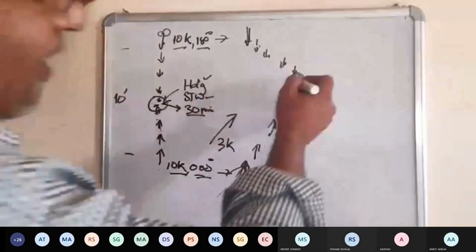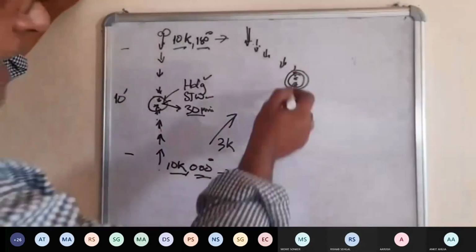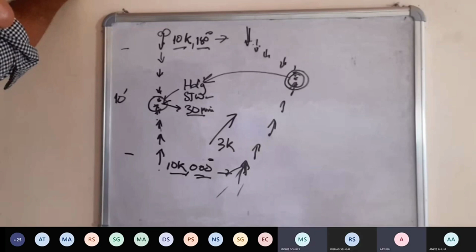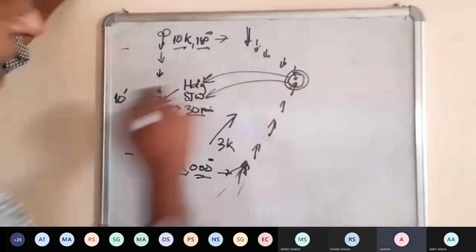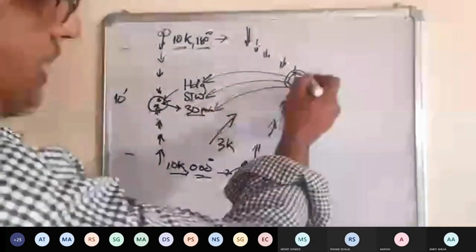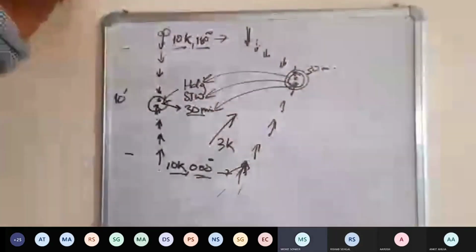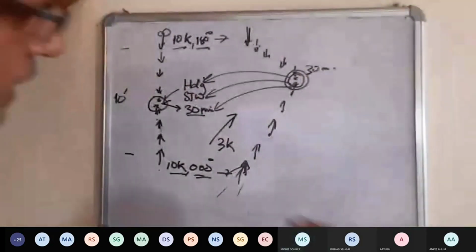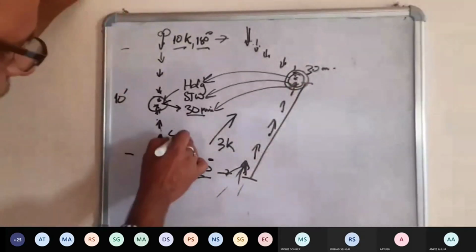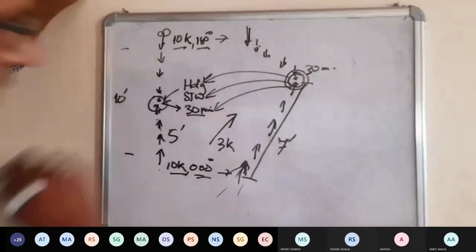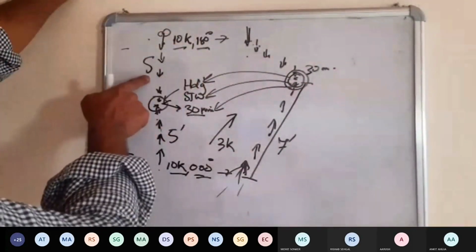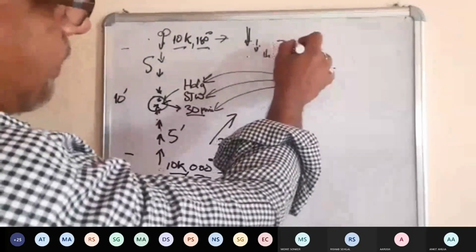Describe the situation of collision here. Is the heading the same? Yes, sir. Is the speed through water the same? Yes, sir. Is the collision time the same, 30 minutes? Yes, sir. Everything is the same. Speed over ground and distance covered differ: maybe here it was 5 miles, maybe here it is 7 miles. The distance covered by this one in 30 minutes is 5 miles, maybe here it is 3.8 miles.